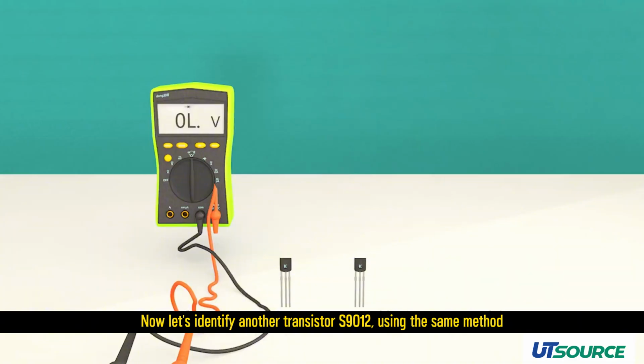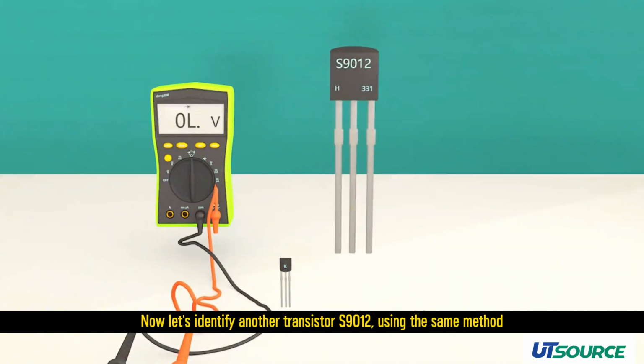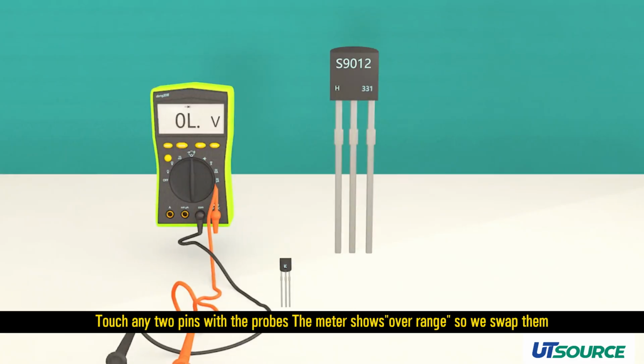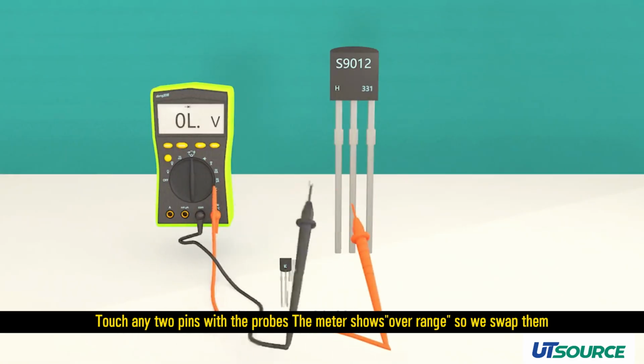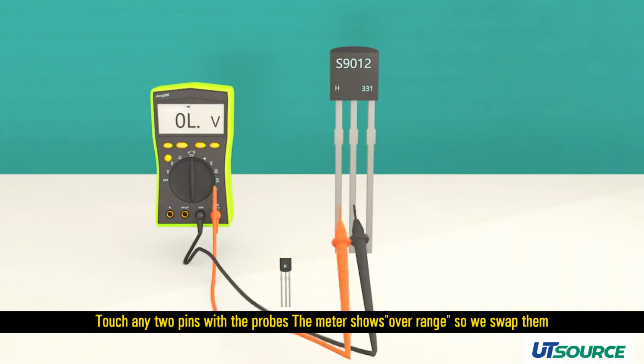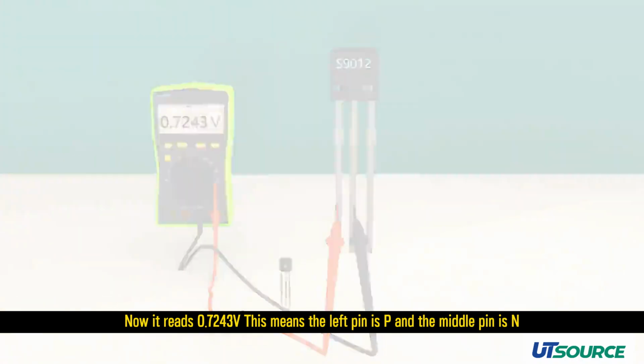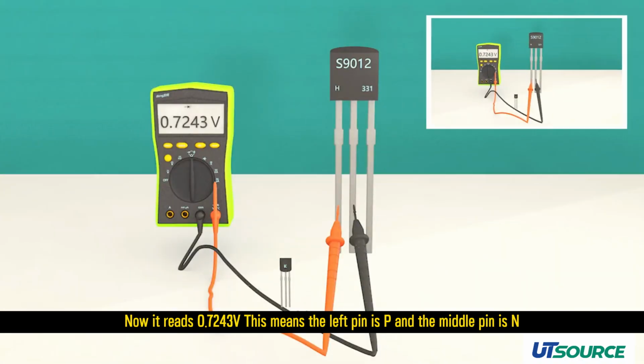Now let's identify another transistor, S9012, using the same method. Touch any two pins with the probes. The meter shows over range, so we swap them. Now it reads 0.7243 volt. This means the left pin is P and the middle pin is N.